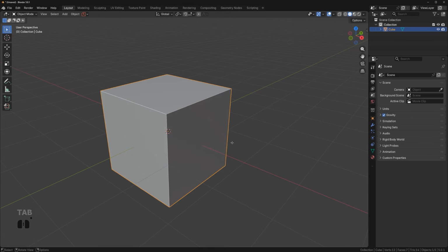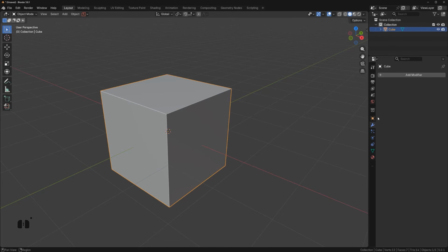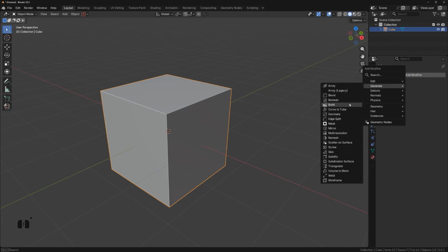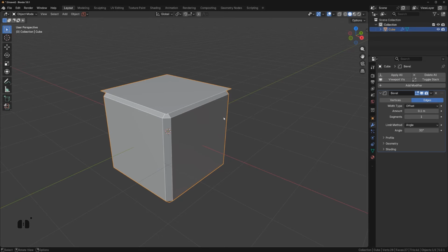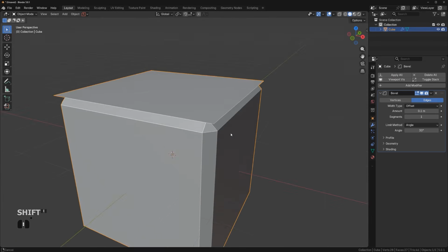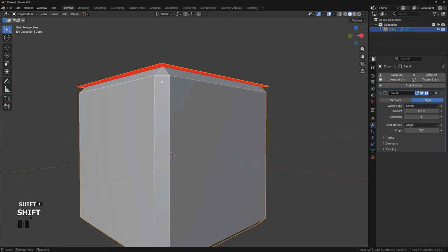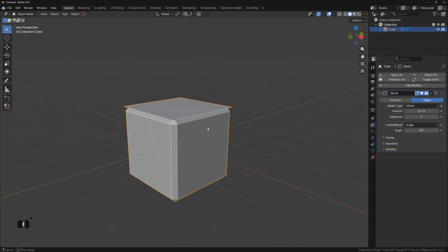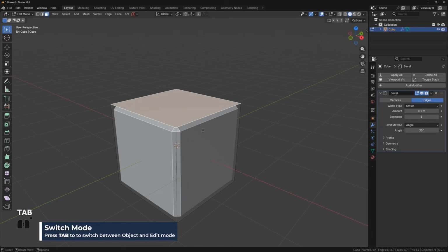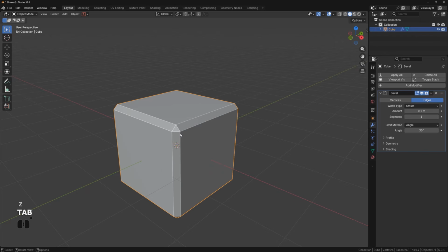So if I go to object view, it's one object. So when I run a bevel on top of this, go here to generate and bevel, you see the problem. This is still part of the object. So what you need to do is go to edit mode, select the face and delete it in order to solve the issue.